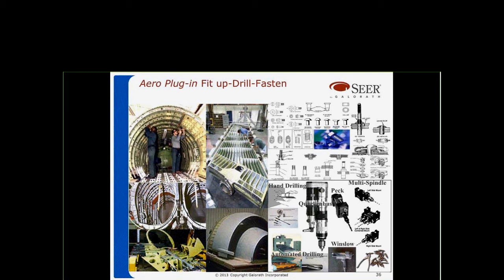It also handles hard shimming and any of your bonding type operations like fay surface seal, water sealing, form and place gaskets, all of the kinds of bonding type operations that we do on aerospace assemblies. The drill operation, you can do Drive-matic or Jobs type automated drilling or any kind of hand drilling, countersink, counterbore, dimple, all of the kinds of things that you have to do in an aerospace assembly.